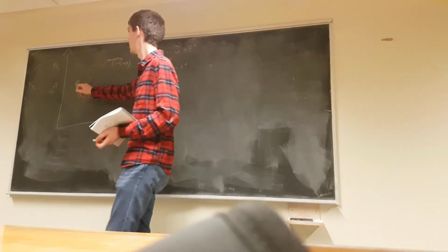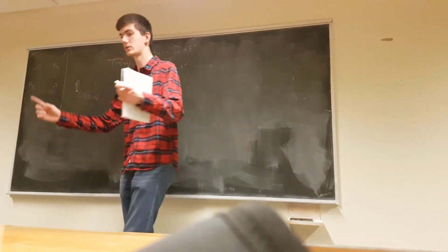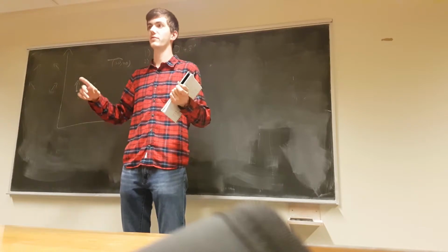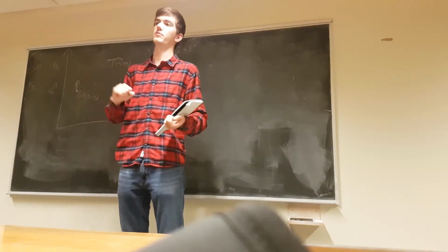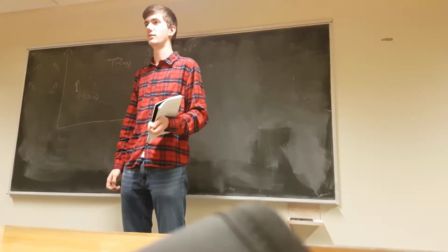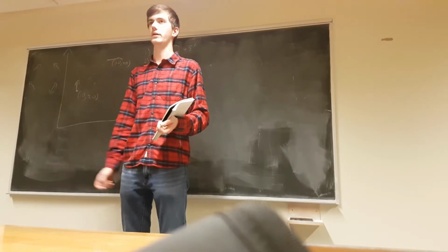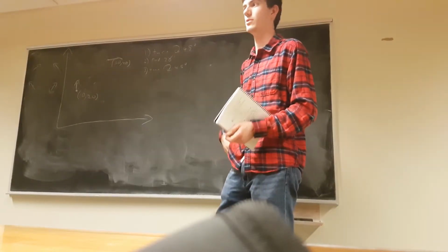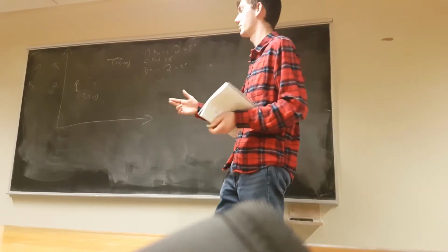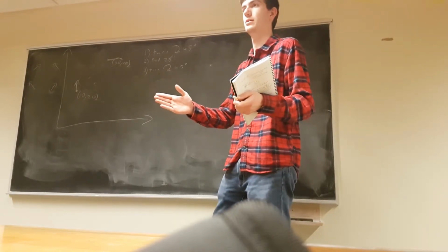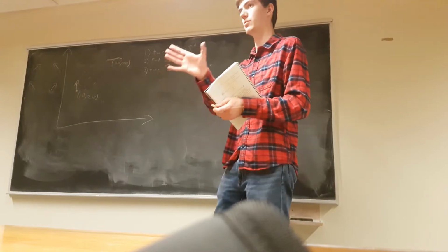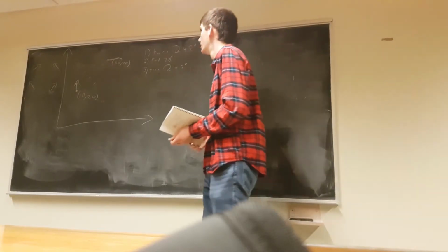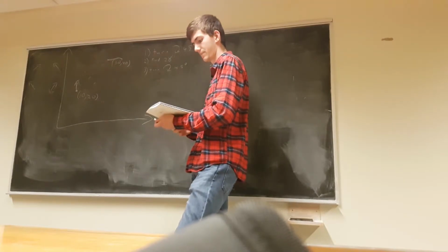What if you weren't just driving? 28 inches is like that much. It's a little over 2 feet, right? The field is 12 feet by 12 feet. What if you're driving across the field? If you were 1 degree off, you can get about 5 inches off. Is 5 inches too much? Well, what if we're talking about a smaller robot that is 15 inches wide? Being 5 inches off, depending on what it needs to do, that could be very significant, right? So that's one issue with it.